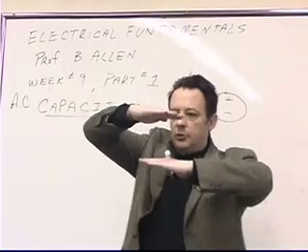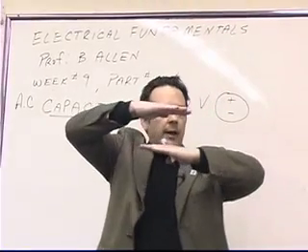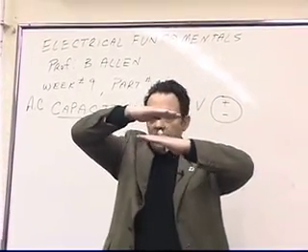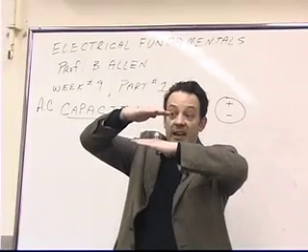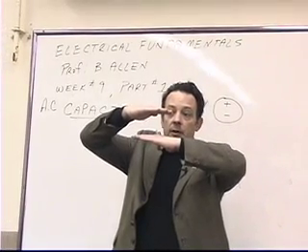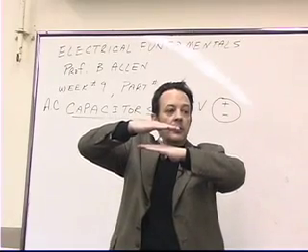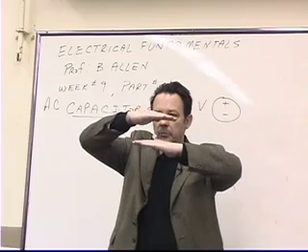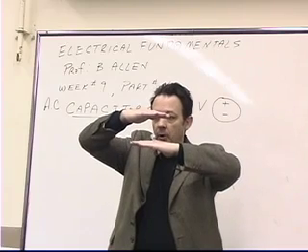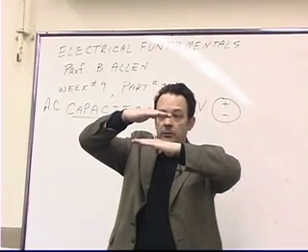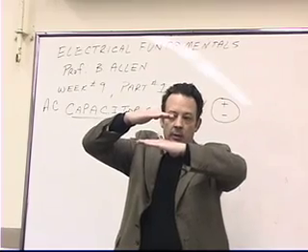If I take these two plates of aluminum and I separate them with some kind of an insulator, like air, then this would constitute the most basic form of a capacitor. It's basically two conducting plates that are separated by something that's an insulator, and in this case, air.